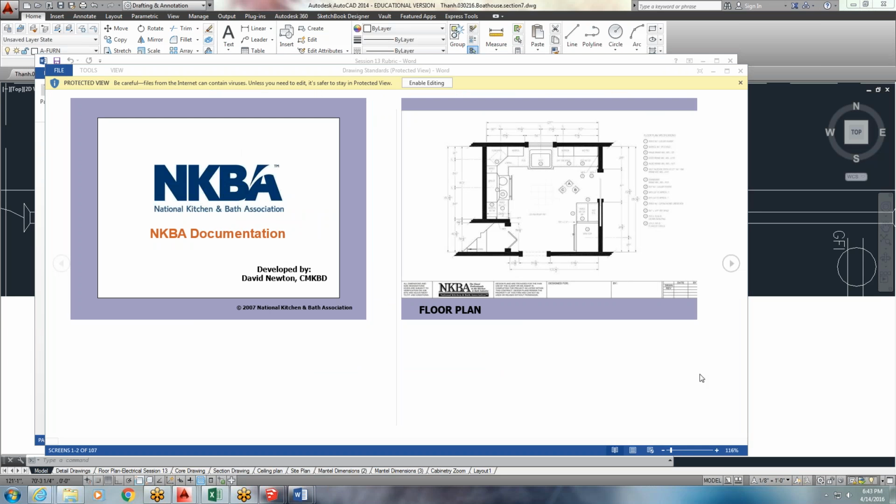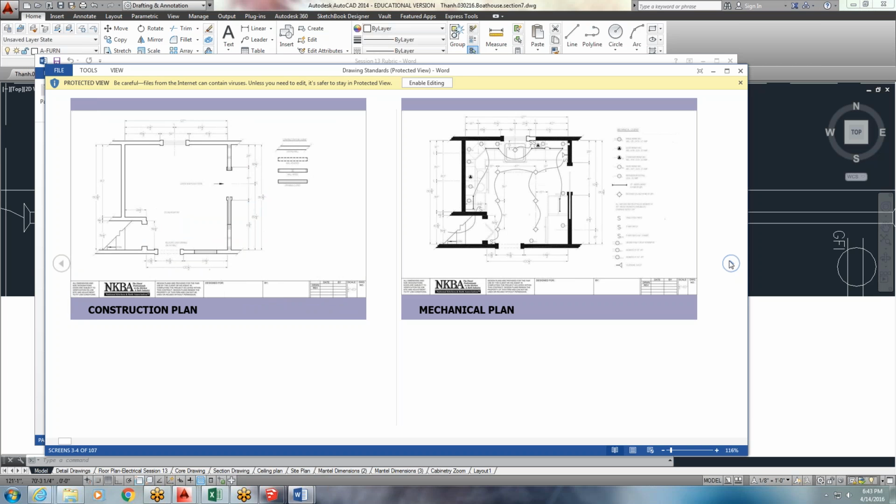Now I'm not grading your kitchens or baths or their lighting according to the rules. I'm just making sure that you know how to accurately bring a set of lights together with lines, connect them to a switch, understand the difference between a single switch and a three-way switch, and the idea that you need at least multiple locations and tasks accounted for within your space. So let's get to this guy.